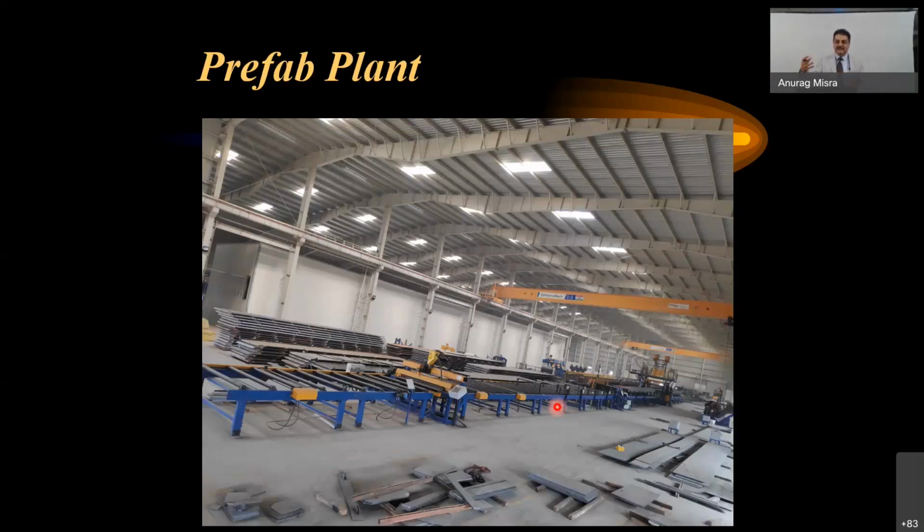So in 15 to 20 minutes, maybe one 10-meter girder is ready. A 10-meter piece. So for creating one 30-meter girder, you need to create three pieces. So 1.5 hours, and if one bridge has got four girders of 30 meter, so maybe in one day you can create one span. So that is the kind of speed we can achieve.